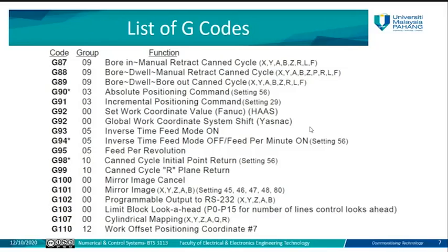Maybe you will ask, do we need to memorize all this code? Not all, but some of the most commonly used coding you need to memorize. Maybe during the test, during the exam, you will be asked what G0 means, what G01 means, or what the machine does in this line, at that address, or at this block, and so on. So you should at least practice more programming using the G code, so you become more familiar with the main commands for the G codes, which are frequently used in the programming of the CNC machines.